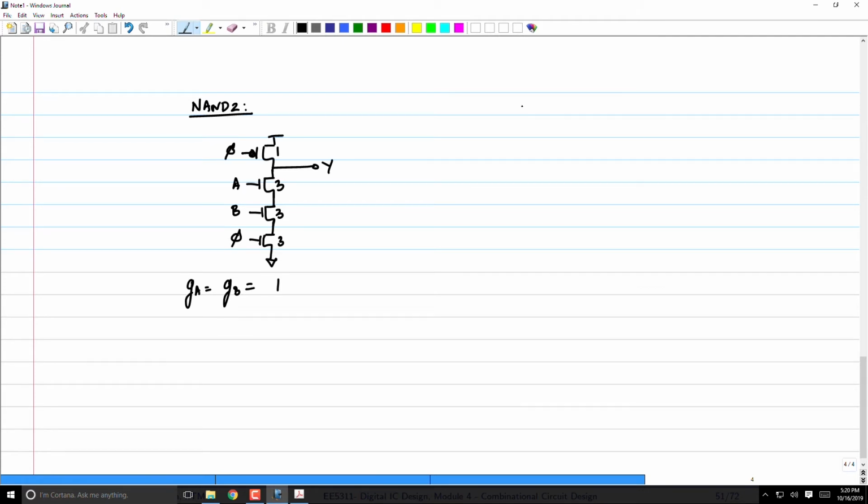Now what about NOR 2 logic? Again, one header device connected to the clock output. Now I need to have parallel logic here, A, B. This is my normal NOR gate. If I wanted a dynamic NOR gate without a footer device, it would be this.